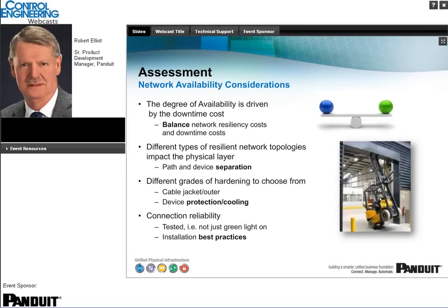Are you getting the expected network performance? Are you experiencing high levels of errors like bit error rate, frame error rates? You should require contractors to provide network performance data on all those links, verifying their performance and reliability. In this picture, for example, imagine if a network cable was running along the top of that door. What would happen to your plant if you lost the backbone network?